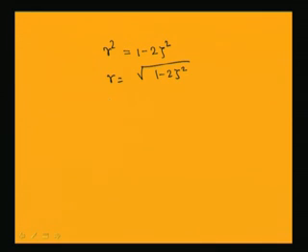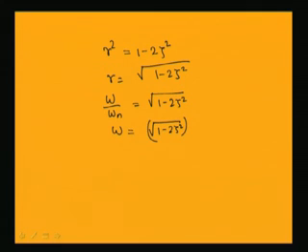So, this is the frequency ratio. For this frequency ratio you can find the response to be maximum, when omega, the frequency of the external excitation, equals root over 1 minus 2 zeta square times the natural frequency of the system. It will have a maximum amplitude.